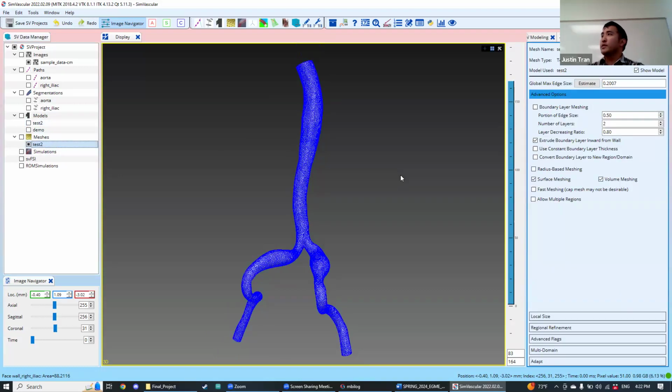All right. Any other questions on this step here? Okay. If your mesh element size is too small, you could be waiting up to an hour for your mesh. So if you've been waiting more than 15-20 minutes for your mesh, you should maybe think about just killing it, and then maybe trying with a bigger size. Close SimVascular, open it again. Maybe restart your computer to clear the cache. So yeah, you want to be careful with the meshing.